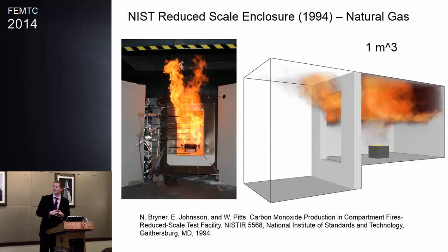The nice thing is that's using 3D volume rendering for looking at heat release rate. So what we do is we look at soot concentration and a 3D slice of temperature, and then Glenn does some magic, and we get a realistic production from SmokeView. The one thing that I want to point out is in that back corner, you can kind of see where the flame is stopped, and it looks a lot like black smoke.